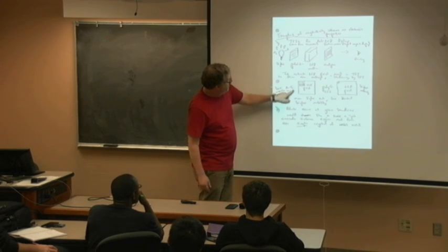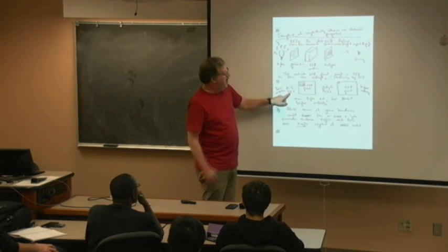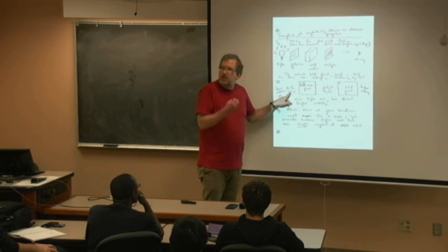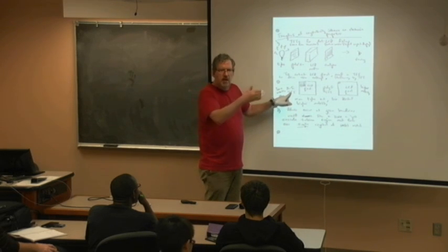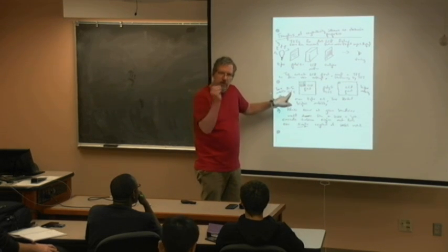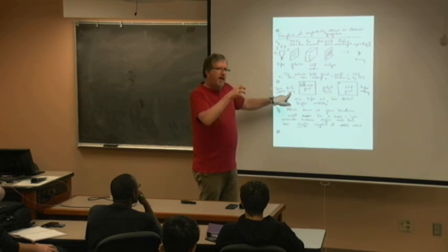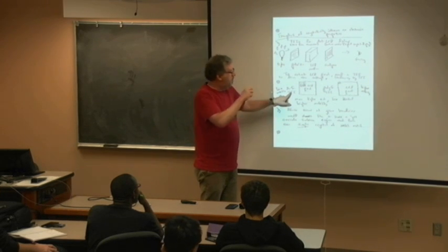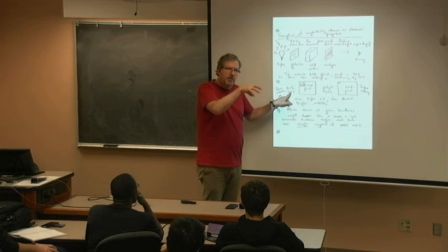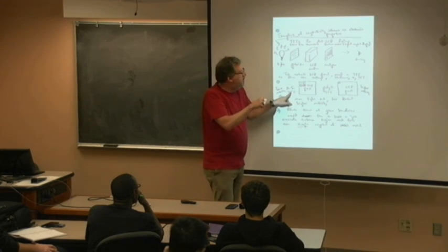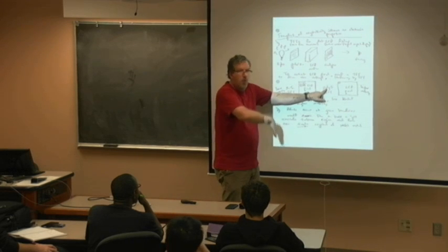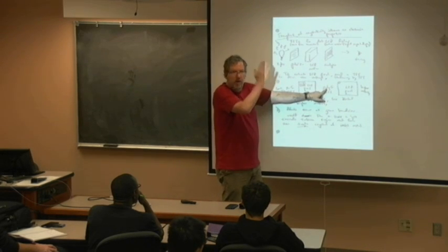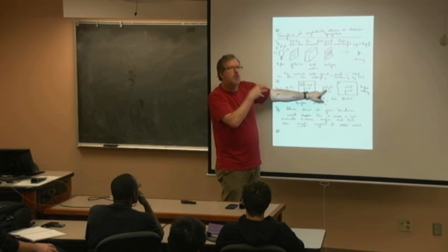So when it is amorphous silicon, due to the amorphous properties, its mobility is very low. Right? It's all that scattering, right? It's just kind of confused. It's an obstacle course for an electron to go through. If I can give it some heat treatment, zap it with a laser and allow it to melt and then recrystallize, then maybe it can recondense like that welding arc that you saw, and maybe it starts to make little grain boundaries.